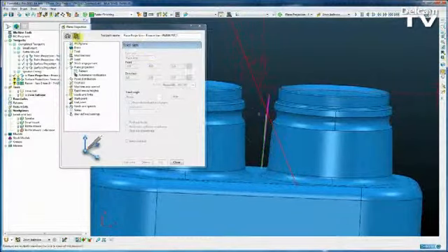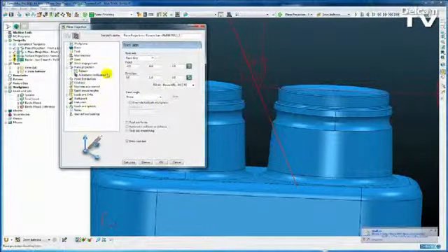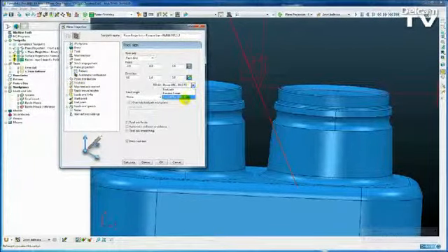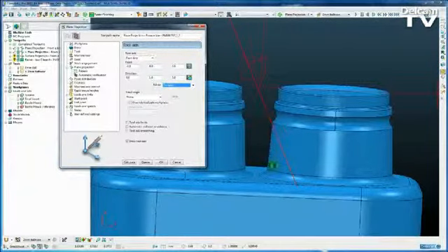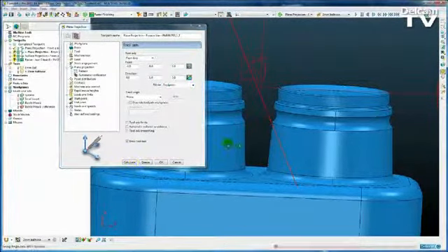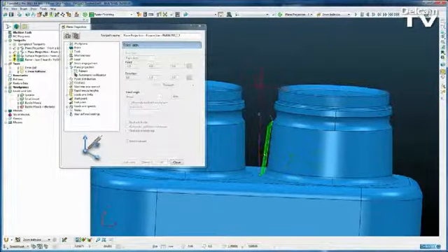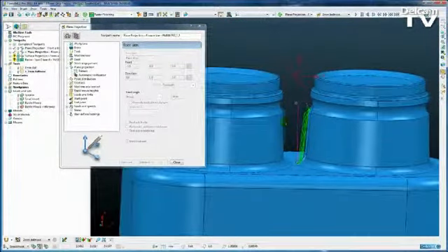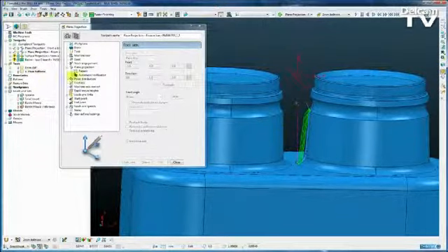So let's just clone that toolpath now and use the new tool axis mode option to give us the correct result with the tool axis exactly as we want it. And to do that we use what's called Toolpath Mode. So the tool axis will be defined on the toolpath at its finished position after it has been projected. So you can see now we have a much neater toolpath that looks correct.